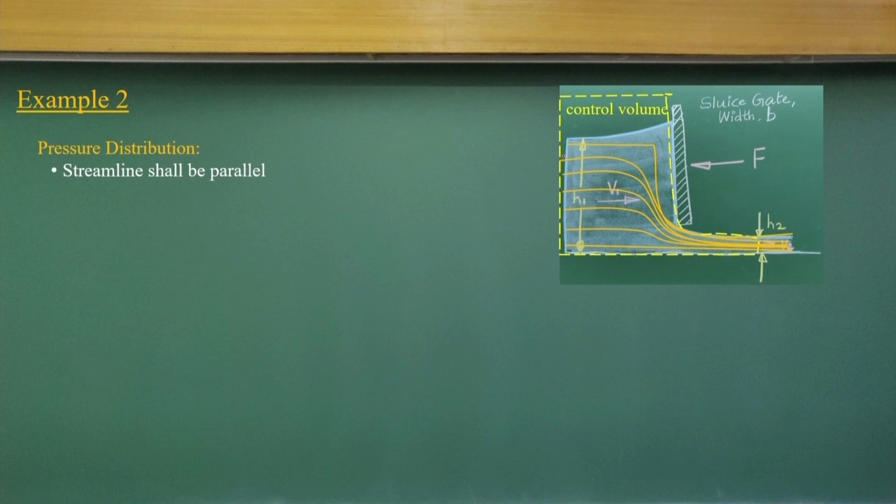If I follow a virtual fluid bulb, it could be like this. So, we should consider the control volume in such a way that, at a far distance, all the streamlines are parallel. There is no curvature of the streamlines where the control surface is cutting across.